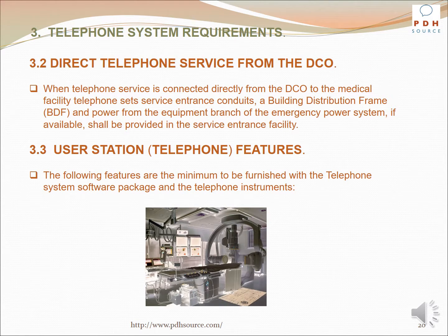When telephone service is connected directly from the DCO to the medical facility telephone sets, service entrance conduits, a building distribution frame, BDF, and power from the equipment branch of the emergency power system, if available, shall be provided in the service entrance facility. The following features are the minimum to be provided with the telephone system software package and the telephone instruments.